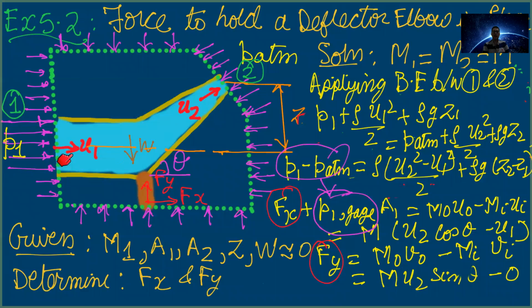But then at the inlet you have a larger pressure. This is an internal flow problem where in certain problems for an internal flow, if you need to calculate the pressure, note that you have to use the Bernoulli's equation. I'm just highlighting why Bernoulli's equation was not needed in the previous problem and why this is needed for this problem. So keep this in mind while solving the problem. So after these 2 problems, let us go to the third problem.